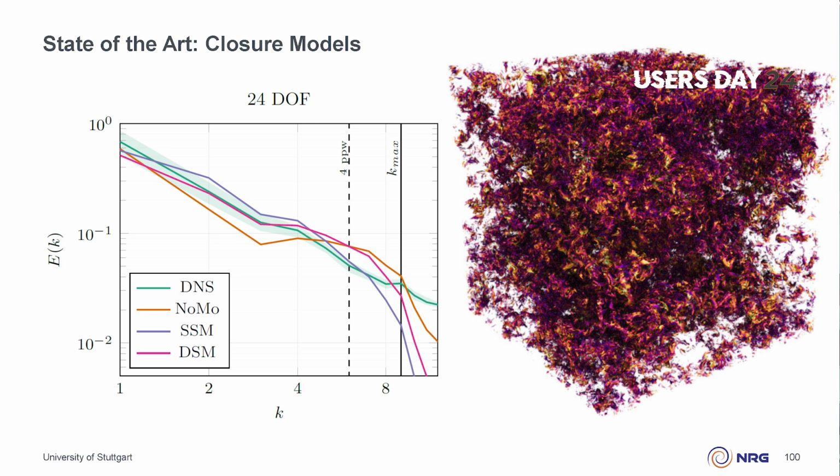So, what you're seeing here is a turbulent spectrum. Let me maybe go back one slide, 2 slides. We're playing with turbulence in a box here, so a very simple toy problem. What you're looking at when you're dealing with such turbulence is the energy distribution over wave numbers, called an energy spectrum. That's the green line that you get from your reference solution.